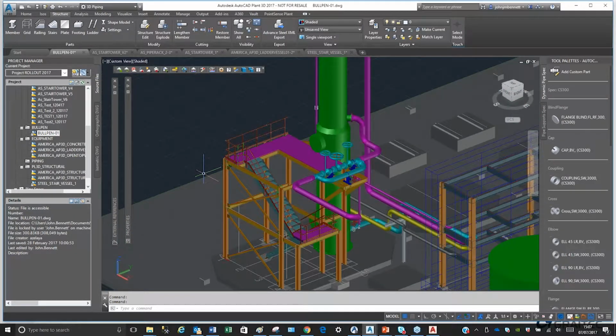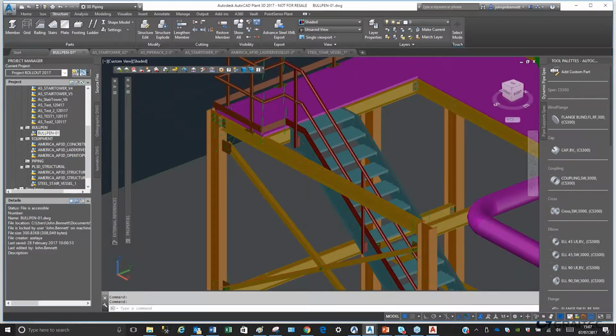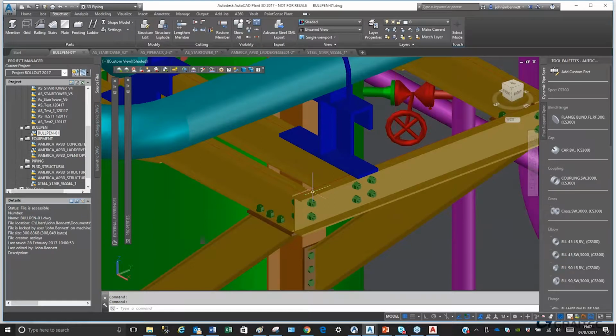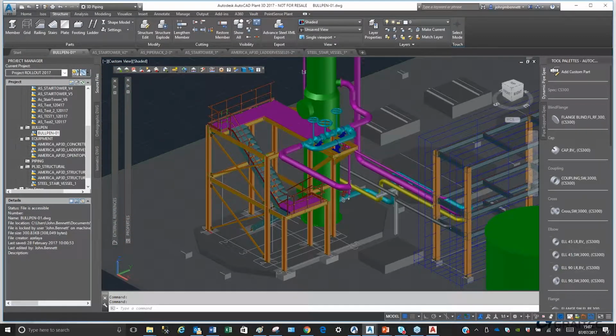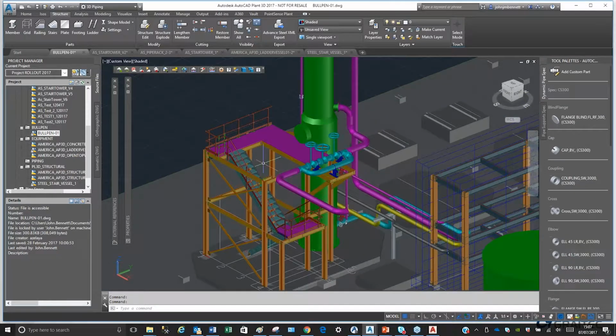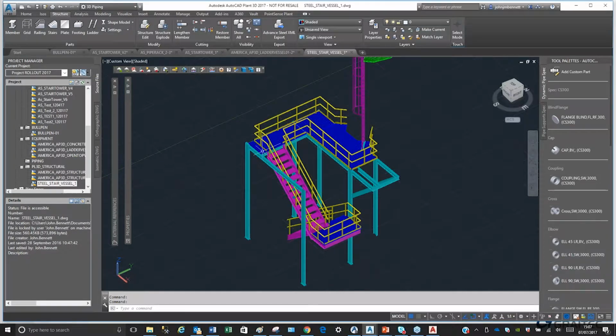So you can see in this project here that I've got nuts and bolts in for the steelwork, and I've obviously tried to marry up with this sort of valve arrangement here and the pipe supports for it. But also I've had to integrate and create a staircase and supporting steelwork for that within the confines of the location and the associated structure. Now originally someone would have probably detailed something fairly basic inside here as what they would understand as a rudimentary layout. But obviously as a steelwork detailer specializing in stairs and connections, etc., you might need to reconfigure that slightly.